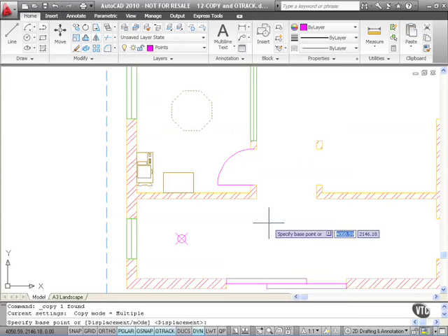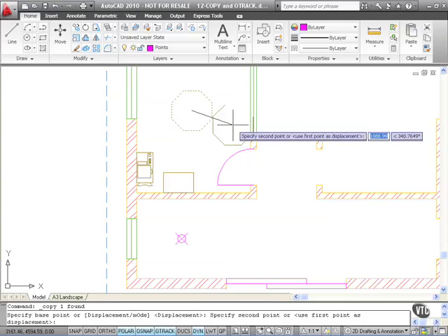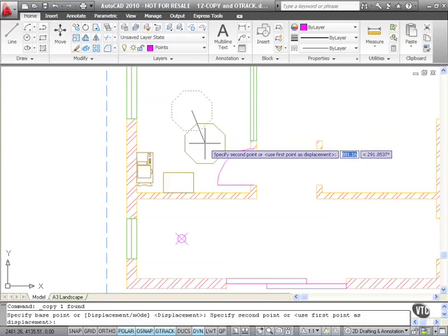I click on copy selection, it asks for a base point. So utilize your object snap tracking to get the midpoint of one of the diagonals or one of the vertical or horizontal lines that forms on the octagon. Watch. I hover there. I do not click. Okay? I hover there. I do not click. As I come in together, there's the intersection, just like with the point earlier, and then I left click for my base point. And now I have the center of my octagonal table.